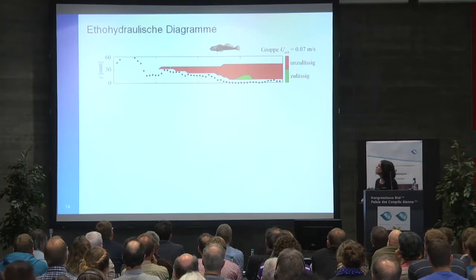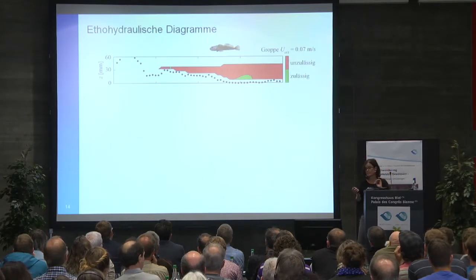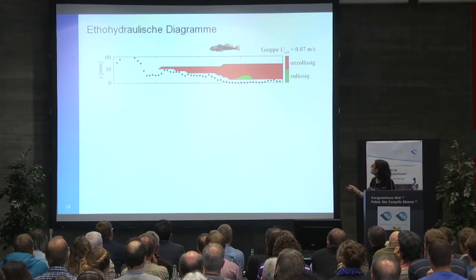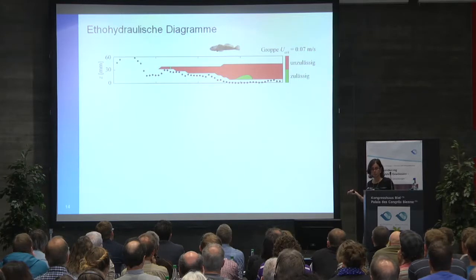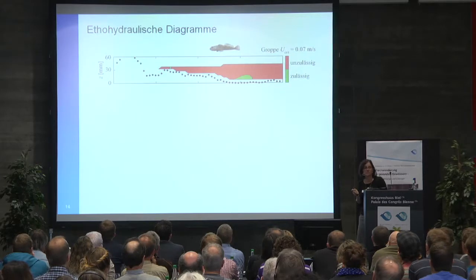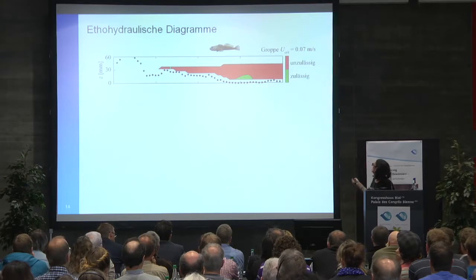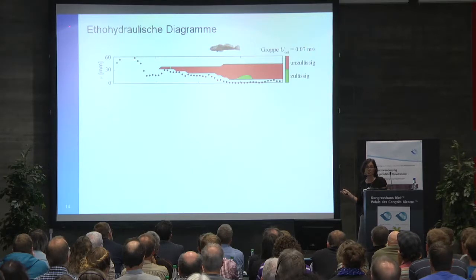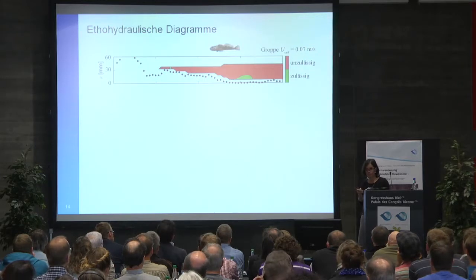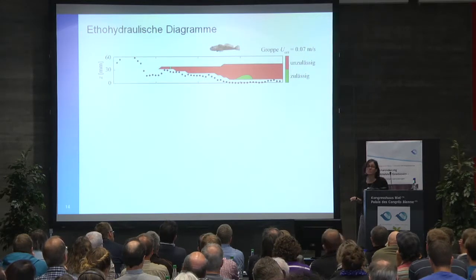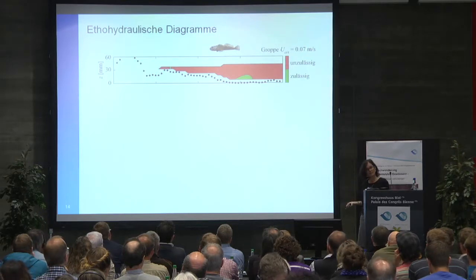With the local flow speed, you can determine hydraulic plots. This is something you've definitely seen before. It's once again that cross-section. You take, for example, one specific fish, such as the bullhead, and I read what speed was required, 0.07 meters per second, and anything that is more is red. So theoretically, the bullhead can't swim against it, and anything below is green.